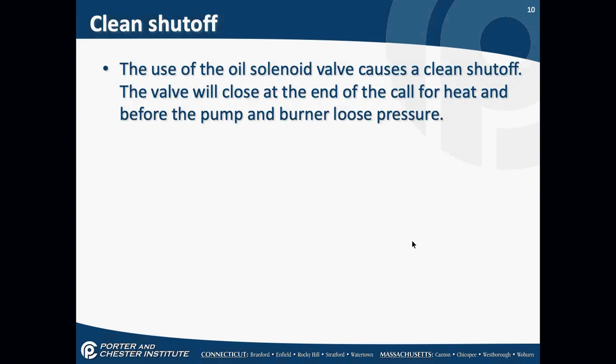Adding an oil solenoid valve solves this problem. It causes a clean shutoff. The valve closes at the end of the call for heat, before the pump and the burner lose pressure. So I no longer have that brief period of time where I don't have enough pressure coming out of that pump.